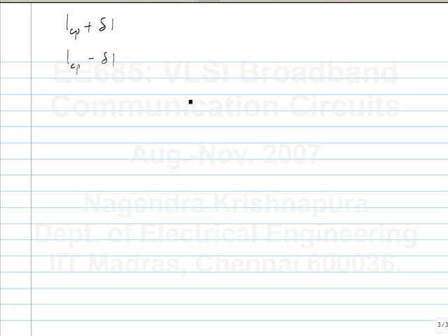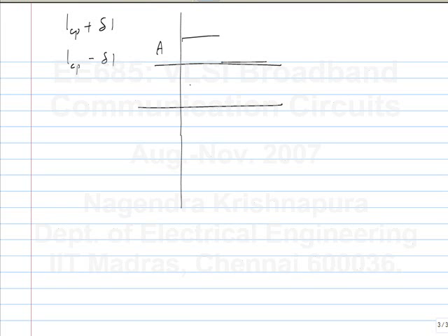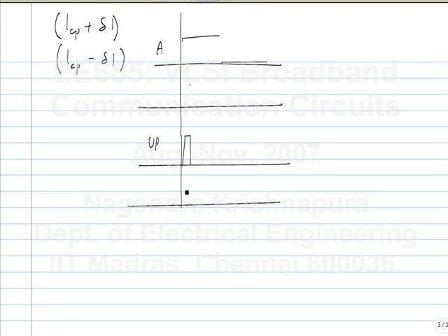2 delta I by. So essentially we have A and B, there will be some phase shift. That phase shift depends on which one, whether the up or down is higher. Okay. Now let's see, if up current is higher and the down current is lower, what we need is for the DC value to be 0, the up should have a narrower width and down should have a wider.